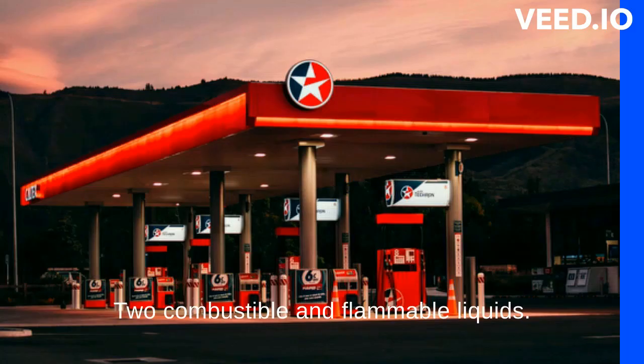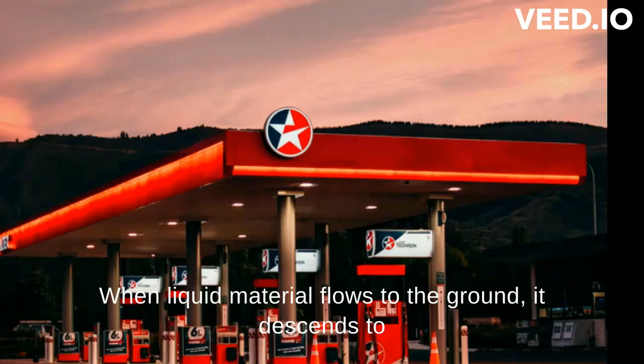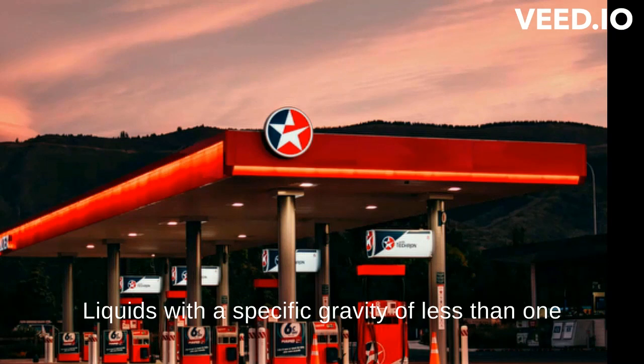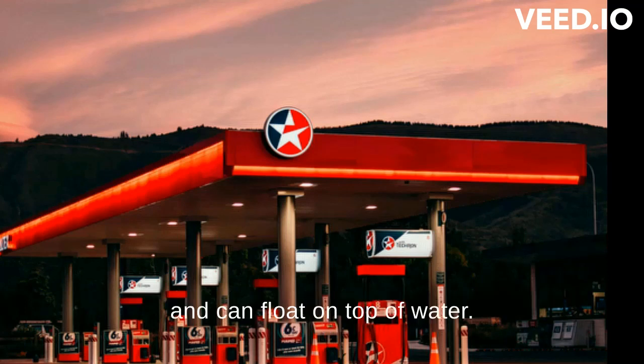2. Combustible and flammable liquids. Unlike gases, liquids do not expand to fill a container. When liquid material flows to the ground, it descends to low areas and forms a puddle in the basin. Liquids with a specific gravity of less than 1, such as gasoline and most flammable liquids, are lighter than water and can float on top of water. Liquids must evaporate to ignite.